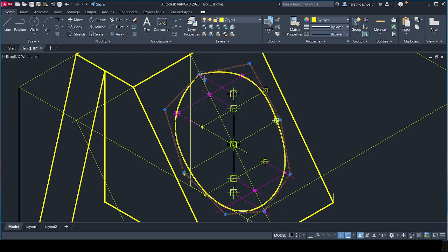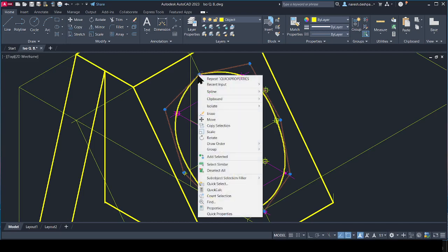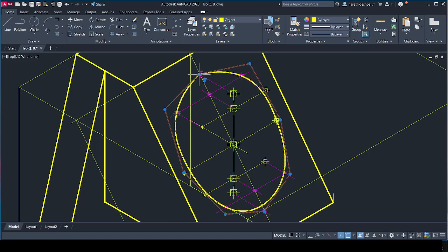We need to add little bit here. Simply just click on this starting point. Just have to move your cursor on the available vertex, then you will get the option to add vertex. So you can add one extra vertex for this curve. It will show the rounding of which one is smooth. You just have to smooth on this. Done. Almost.